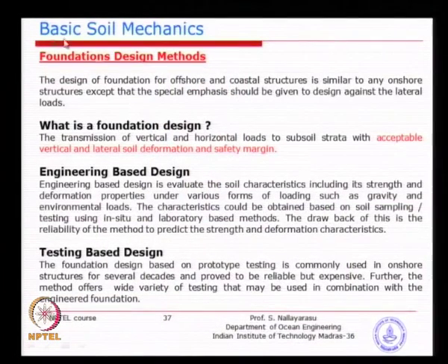The next method is the purely engineering based method. For example, if you have an onshore site, you could do this testing, no problem, because you can mobilize all this required. If it is a coastal site, it can also be done, because you can construct a temporary platform from which you can do the loading. Whereas, if it is an offshore platform in 100 meter water depth, doing testing by any means is impossible.